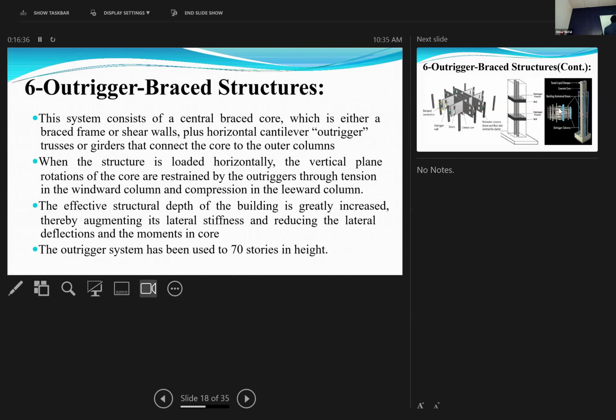So when this building gets hit with an earthquake, whatever this earthquake looks like, let's say this is the acceleration of the ground, there's a base force hitting the base to shake the building. So this building wants to turn that way. There's a bending moment, like all the masses want to be thrown that way. So there's a bending moment on the shear wall. If you look at the stresses of the shear wall, there's a lot of tension here, a lot of compression here, and this is the stress down there.